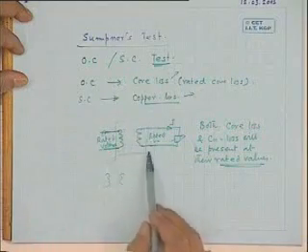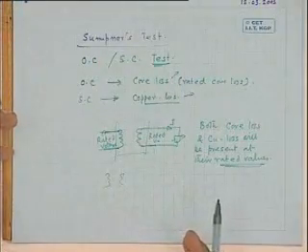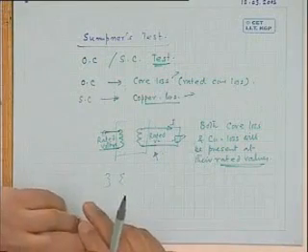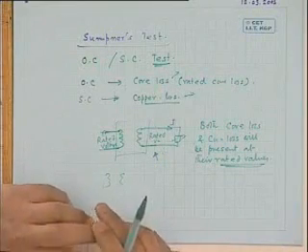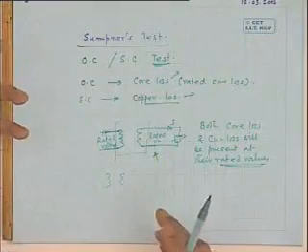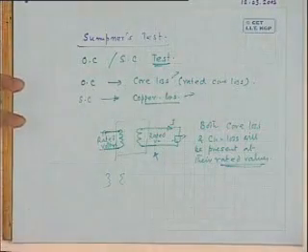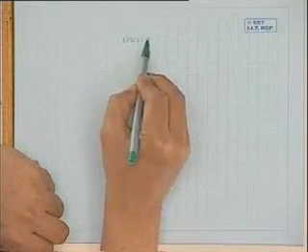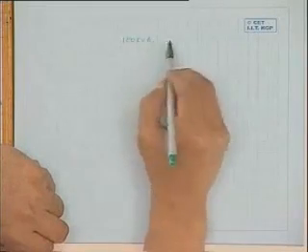If you connect a wattmeter, inside the transformer both the core loss and the copper loss are taking place. You have loaded it. But what is the objection to this load test? Power dissipation. Perhaps for very small transformers you can carry it out in the lab, say a 5 kilowatt transformer, with a 5 kilowatt load like that. Imagine you have a distribution transformer whose rating is say 100 kVA.